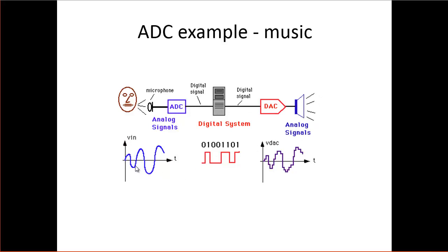And so this right here shows you the signal going into the microphone is continuous. The signal coming out is digitized, so there's a little bit of an error in there. So certainly you've heard the effects of this when you listen to, say, an MP3 that's been compressed a lot, and it doesn't sound quite as good as the original signal because you've lost some of the information. In the case of an MP3, some of that loss of information comes from the compressing and not directly from the analog to digital conversion process, but the idea is there.